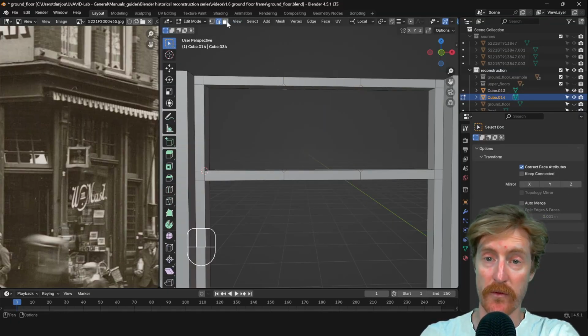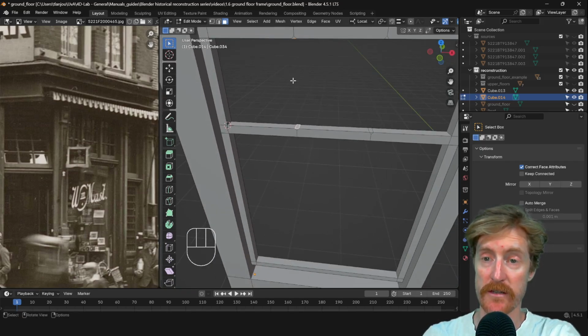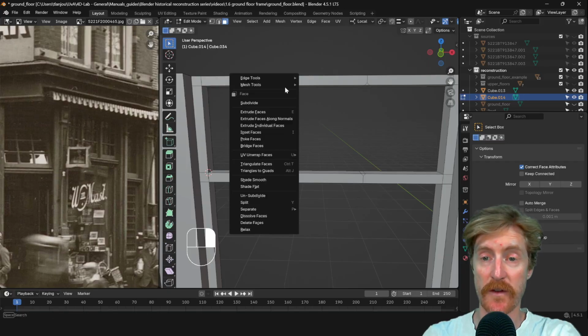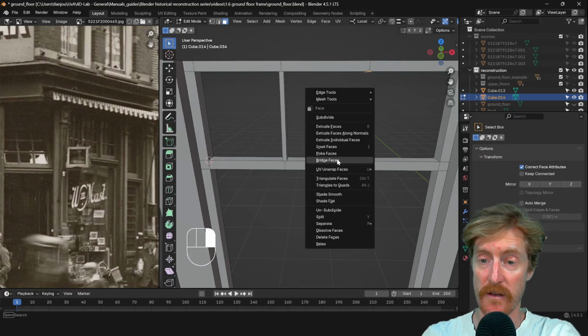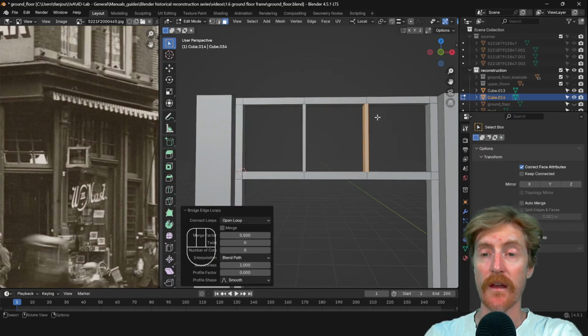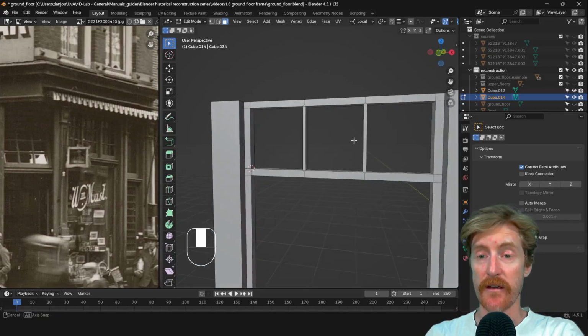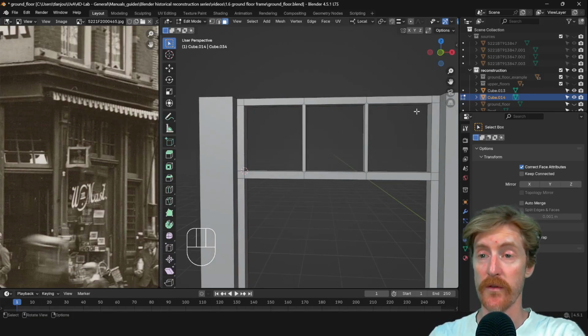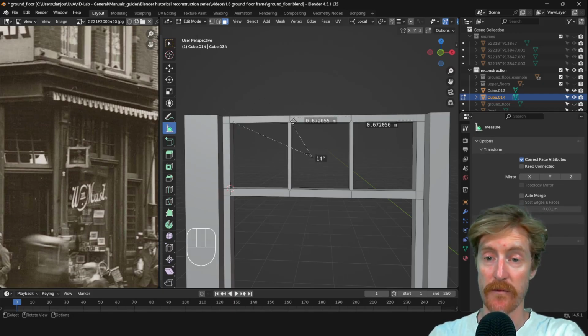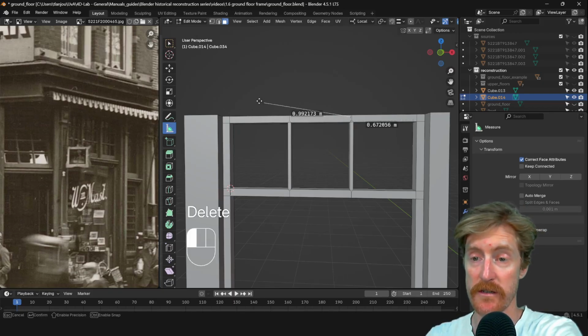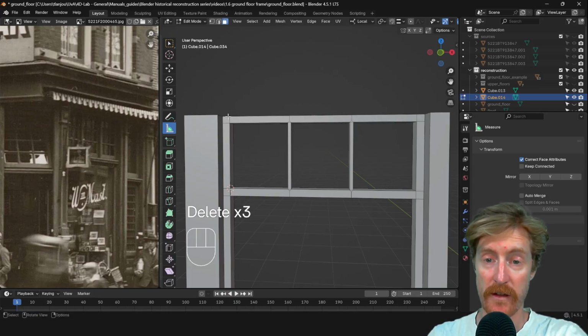Turning off the bevel tool, face selection mode on, and I will select the opposing faces and then bridge these faces. So bridge faces, and over here bridge faces. Now it seems like we have now created equal divisions, and that is partially correct. If we would want to measure this, we can measure this to double check it.